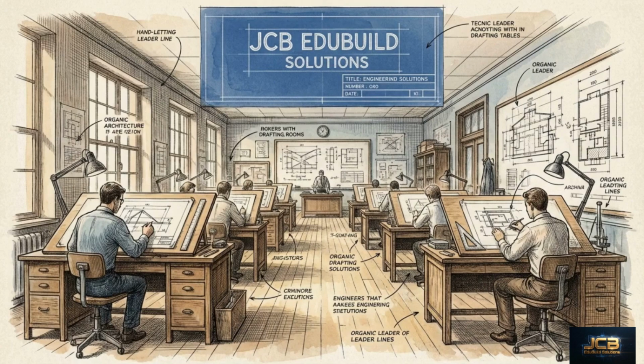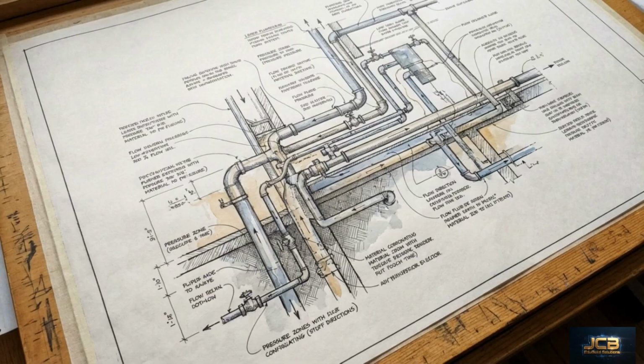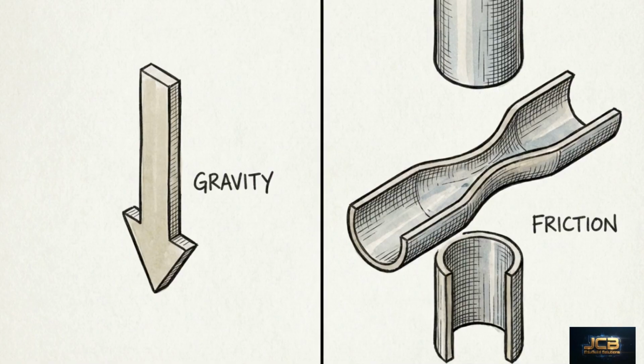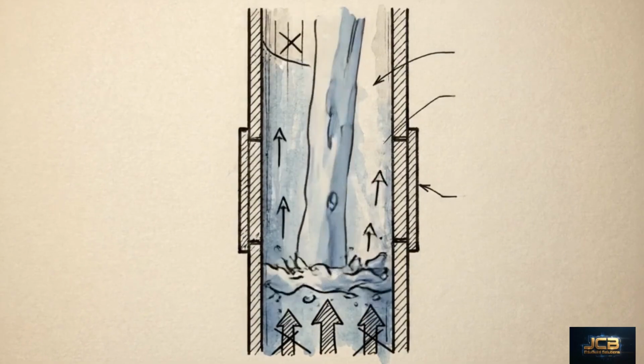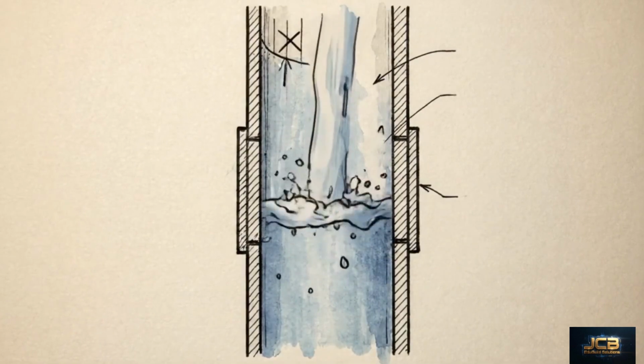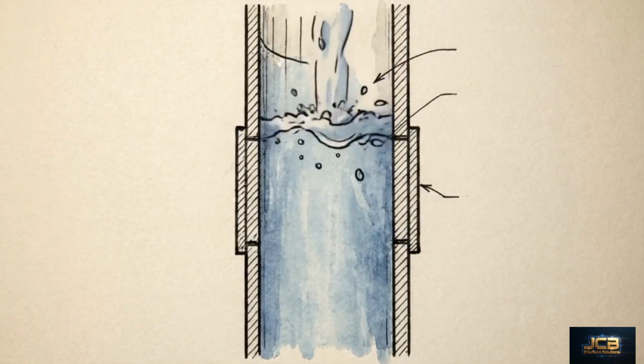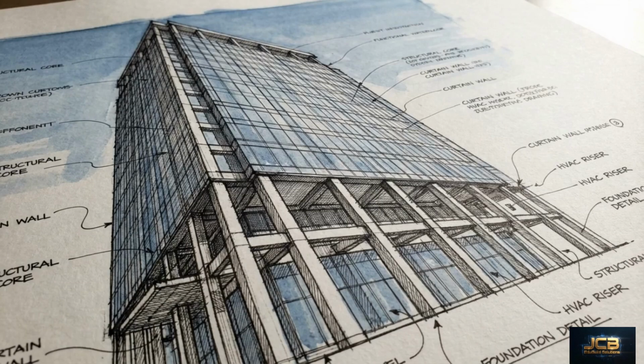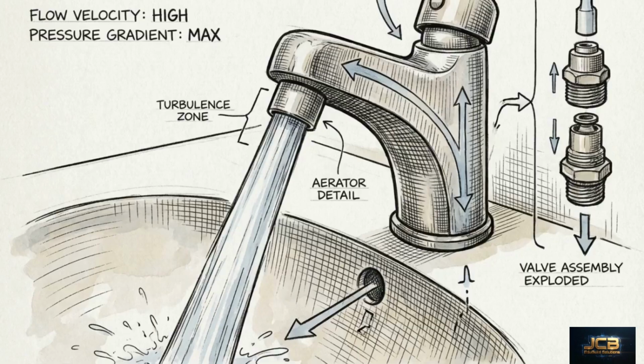To all our engineering specialists and board reviewees joining us today, let's dive straight into the mechanics of sizing water systems. The physical challenge of plumbing design comes down to two inescapable forces, gravity and friction. As water climbs through a high-rise, it bleeds pressure. The higher it goes and the more pipe it scrubs against, the slower it moves. The ultimate objective for the plumbing engineer is to guarantee that the highest and most remote fixture in a building operates at code-compliant pressure during absolute peak demand.